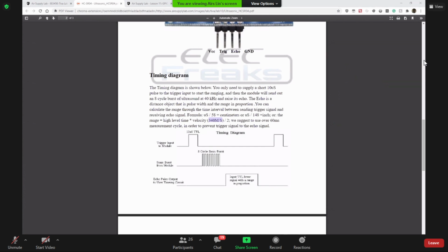Okay. And also this one is pseudocode. This one is not the correct code. So also need to implement this one. The period of the cycle is one over the frequency. What is the frequency for this one? And the system clock I changed to 80 megahertz. Yes, okay. See here, this is 80 megahertz. So your system frequency is 80 megahertz. So times one over the 80 mega. Yes, you need to divide by 2. Okay. You can check here.